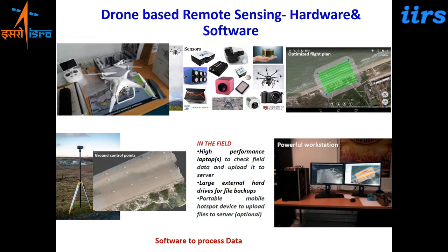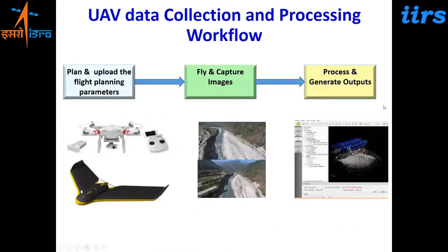Then you need a powerful workstation to process these data sets, and software to process this data. Right? So you have the entire UAV data collection and processing workflow, where you need to plan and upload the flight planning parameters using the mission planning software, fly and capture the images, then process and generate the outputs.